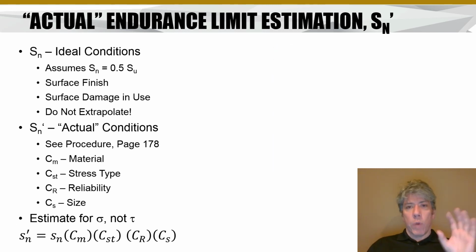Now, remember, what we've been talking about so far is all for normal stresses. Even a bending stress is a normal stress, so it applies here. We're not talking about shear stresses. Like I said, if you want to understand shear stresses, read in the book about how you combine. You just use Mohr circle and then use either the distortion energy theorem or another one. I can't remember the other one right now, but one of those two is what you use to combine the stresses after Mohr circle into something that generalizes the approach that we use here.